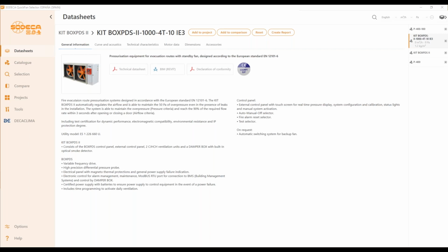Well, I would not recommend installing them as compensation for corridors. The purpose of a backdraft damper is to avoid backdraft flow, but we cannot control the difference of pressure when they open.